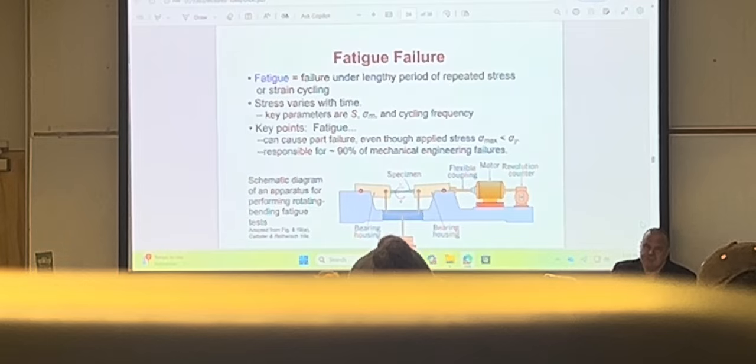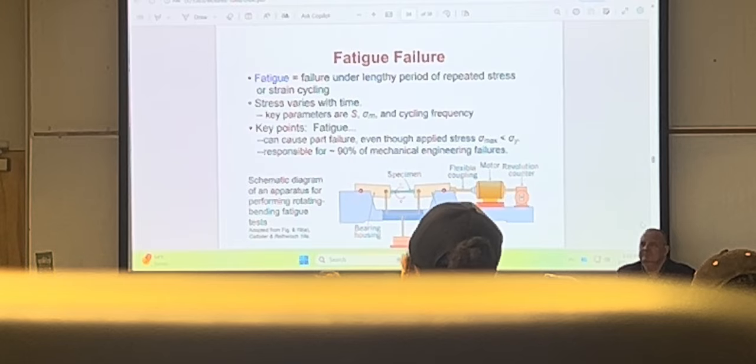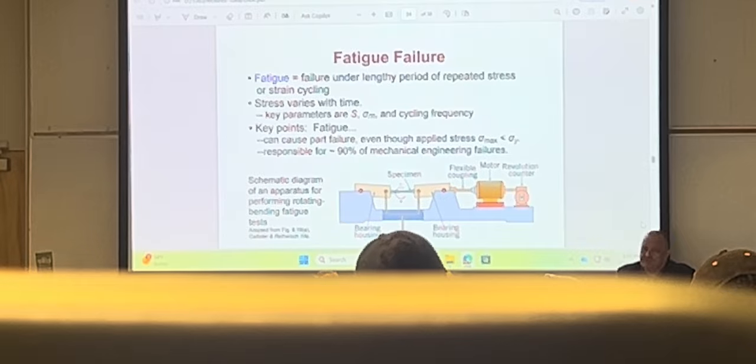Normally, if a car is driven, you get 10,000 miles per year, so the car was at least 12 years old, right? How old was the car? 12, yeah, 12 years old. Okay. So why does it happen? Why does the new car not have a CV boot failure? It's fatigue. So fatigue has to do with the number of cycles.